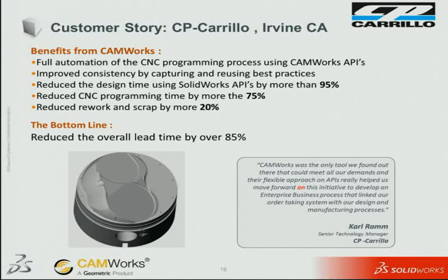So there's lots of ways to create stock, and they're all pretty easy to use and pretty automatic. In my particular example, I had a sketch that I used for the plate, and I had used that as stock, and in that case, CAMWorks used that sketch automatically.